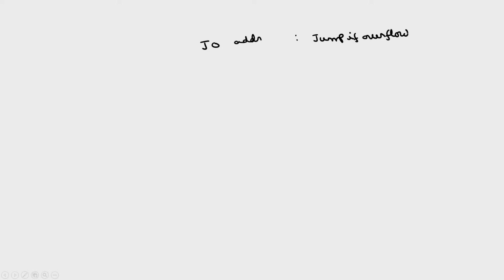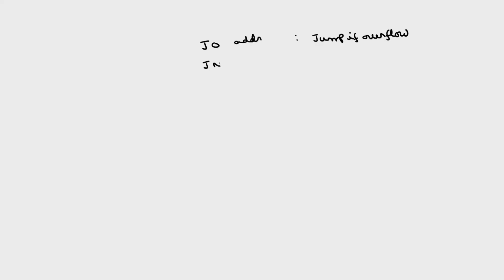This JO stands for jump if overflow. In signed numbers, we have a range of numbers. If the result is outside the range, then the overflow flag will be set. This we have discussed while discussing these flags. Jump if no overflow. So, here total 10 instructions correspond to 5 flags. For the remaining flags, there are no jump instructions.